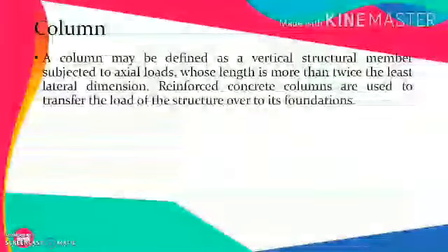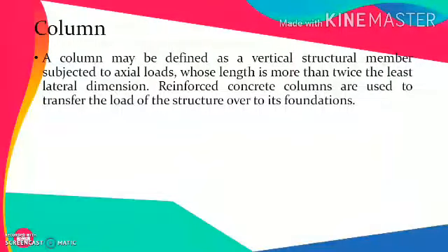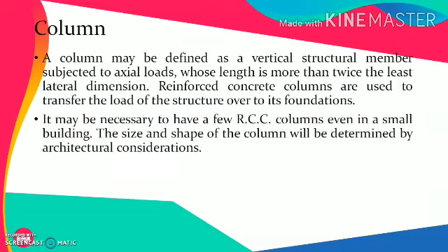Column. A column may be defined as a vertical structural member subjected to axial load, whose length is more than twice the least lateral dimension. RCC columns are used to transfer the load of the structure over it to the foundation. It may be necessary to have a few RCC columns even in a small building.